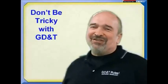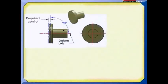This month's tip is, don't be tricky with GD&T. Let's say that the primary datum feature on this part is going to be this smaller diameter, which will establish an axis. The secondary datum feature is going to be this face, and I want to control its relationship back to the axis. It's a 90-degree relationship, so I want to keep it perpendicular.